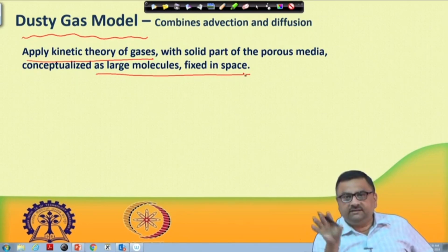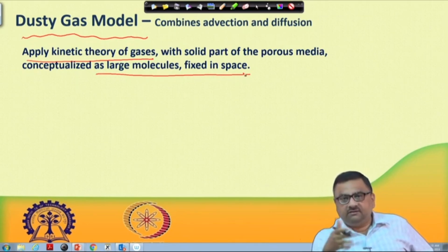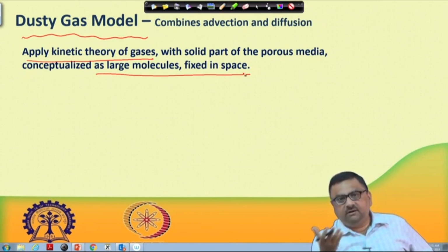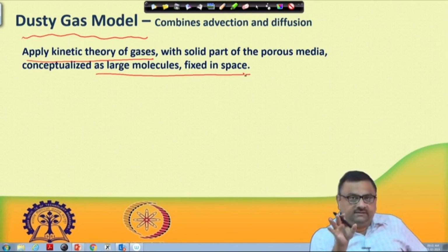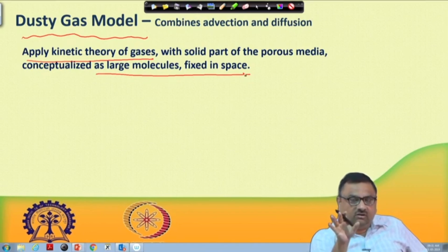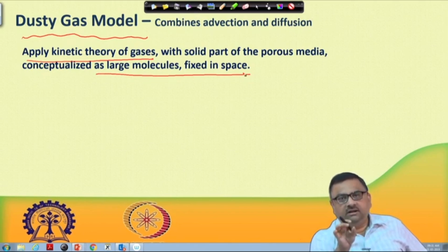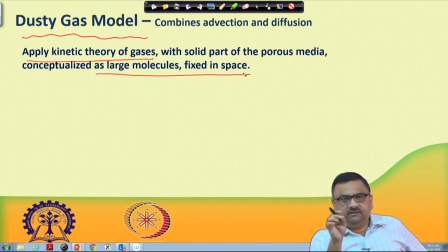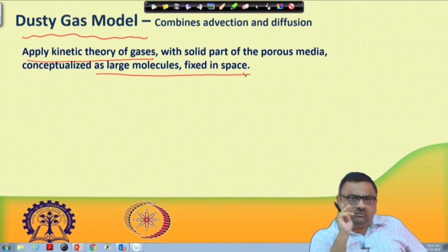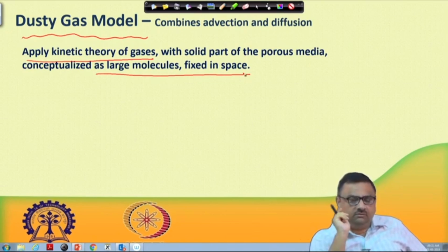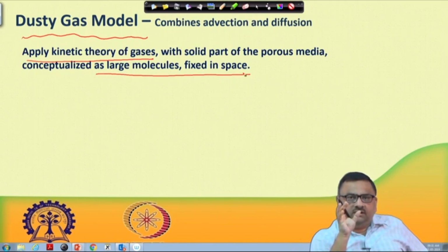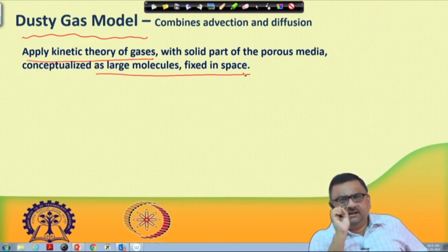And now, let the kinetic theory of gases play out and work out, and based on this one can find out what would be the transport of penetrant molecule, what the rate will depend on. So, this is essentially the dusty gas model, and there has been a good amount of literature already established. These are basically the transport mechanisms that we have talked about so far. These are essentially all the transport mechanisms. Now, two things you have to keep in mind here. I must point out, one is that these models that we have talked about so far are basically one phase system.